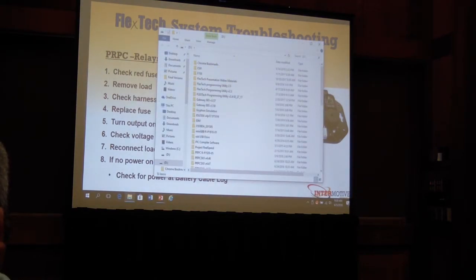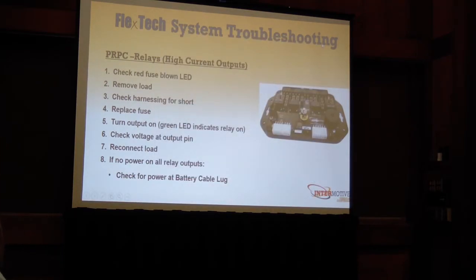There's a number of different configurations for the relays. 1 and 2 and 7 and 8 are similar configurations, so they're just 12 volt outputs. There's another build of the module that allows motor reversing on those outputs. So in the normally closed state, they would be providing ground out on the pin, and you can reverse them, provide ground, run the motor one way, run the motor the other way. So that's 1 and 2, and 7 and 8 can be motor reversing pairs.